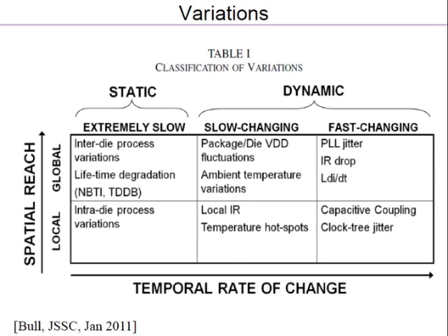Now you go back and think about the doping concentration. We are talking of channels which are very small, because as you're scaling down, you can have maybe 1,000 dopant atoms in the channel, maybe less. Physically, where are the dopant atoms? If I take two transistors, maybe in one transistor there is a certain distribution of the dopant atoms in 3D space. In the second, it might be a little different, because the dopant atoms are coming in from the top. They are bouncing off and falling in. Maybe they are entering through different trajectories and get embedded. You don't know. The number which will get embedded also you don't know.